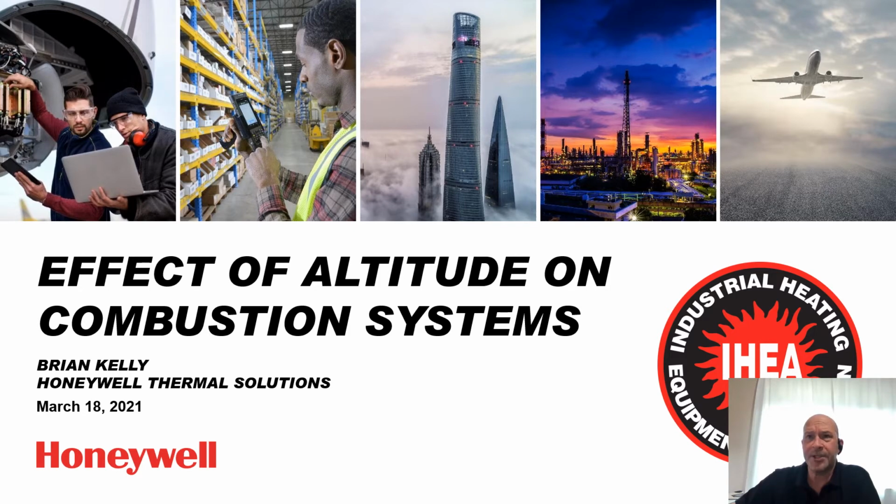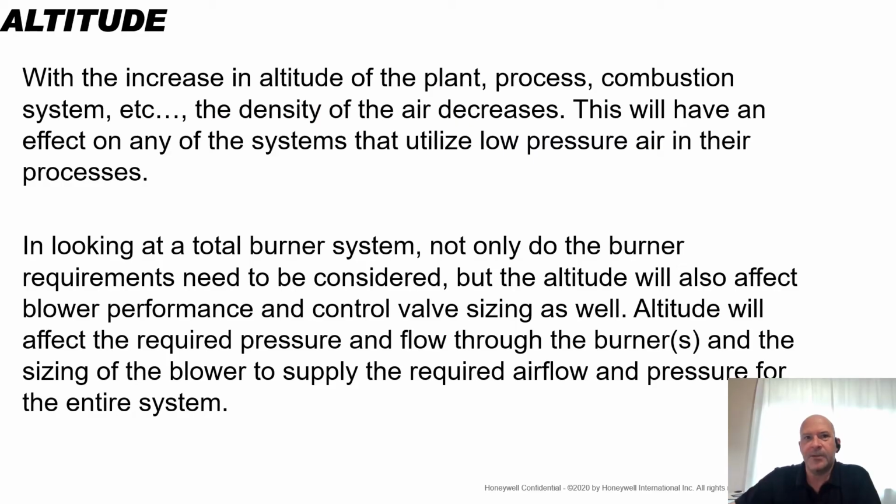I'm Global Applications Engineering Manager at Honeywell Thermal Solutions, and our subject for this video tip today is the effect of altitude on combustion systems. With the increase in altitude of your plant, process, or combustion system, the density of the air decreases as you go up higher in altitude. So this is going to have an effect on any system that uses low pressure air in the process.